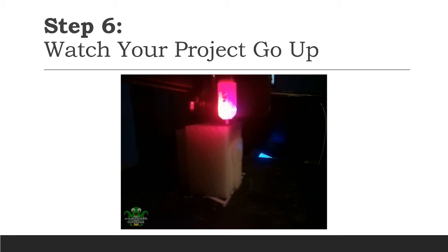Alright, so now that we've had it submerged for a little bit, it's going to be a lot easier to take these supports off. It's still not going to be super easy. Some you'll be able to take off real easy, and you'll see it completely off right there. And then this one might take a little harder. So what I recommend is taking one of your tools here, and just prying it in there, and boom, it comes right off, leaving a nice clean area. And then this just little tiny guy right here comes off, and you have all your supports done.